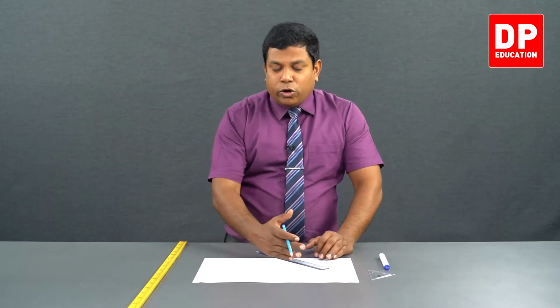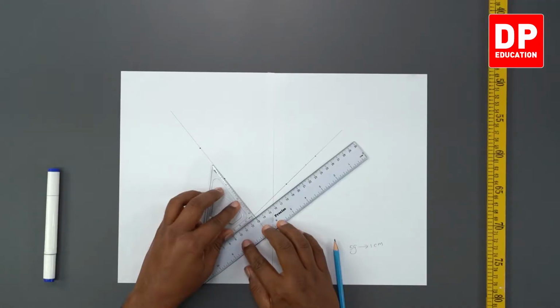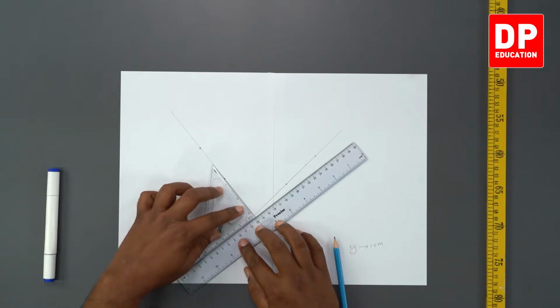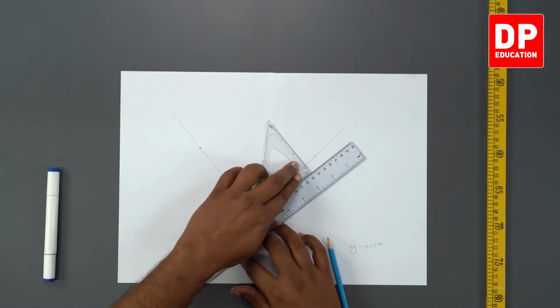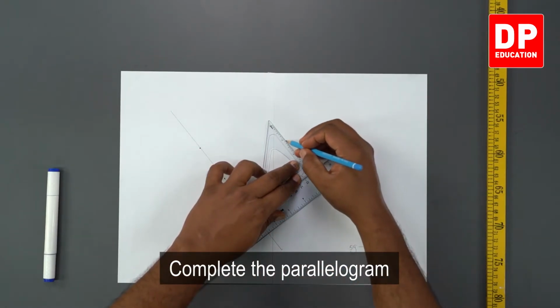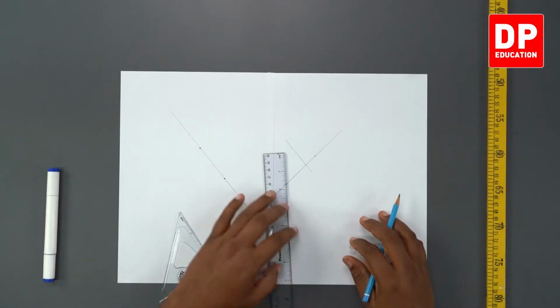Now what I have to do is draw parallel lines. Either you can use a compass to draw the parallel lines. If not, we can do this. Keep the set square parallel to the line and support the other side of the set square with the ruler. Now move the set square, take it to this 10 centimeter point and draw the line. Extend the line.